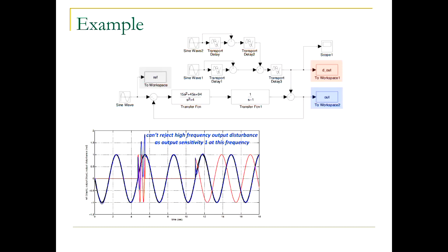But whenever we hit the system with some disturbance, there will be some small transient. When we hit it with a disturbance of frequency 2, the error will converge to 0. Whereas if we just kept this high frequency disturbance, we will never converge to 0. The controller would just not be able to cope with it. So this shows you in action how the internal model principle works, on a very interesting example.